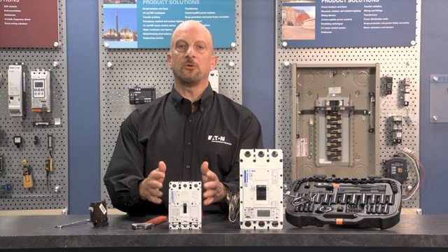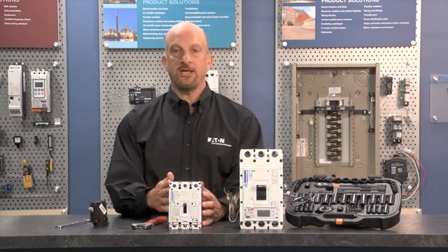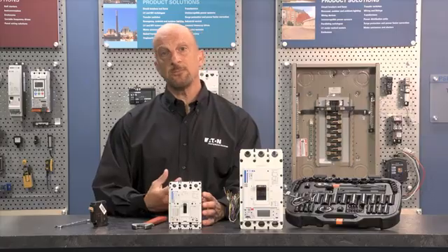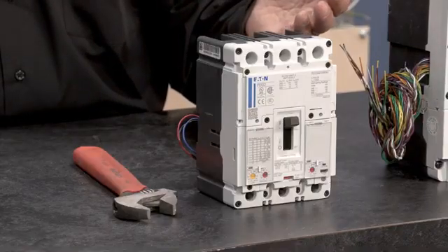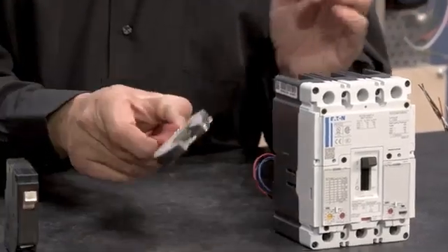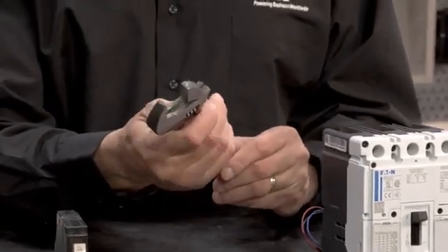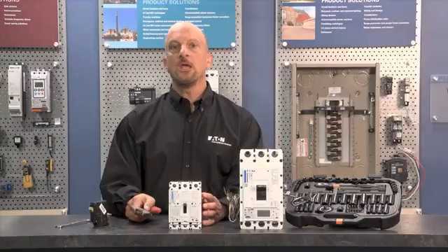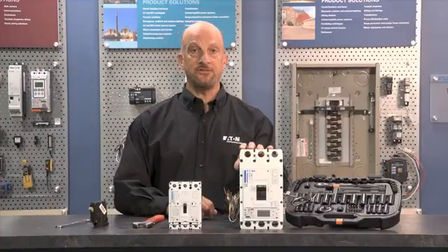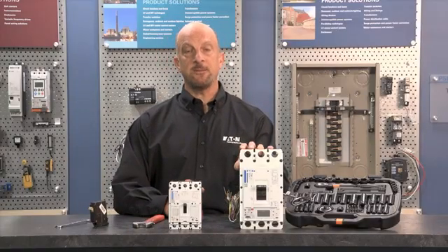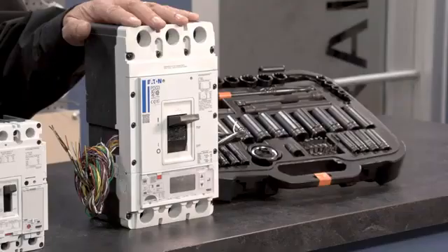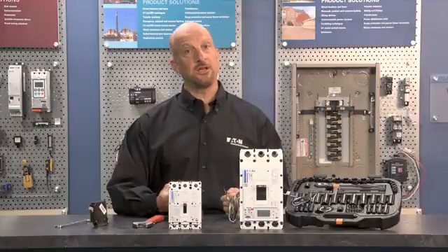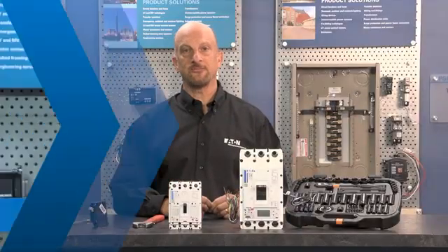The next type is also a thermomagnetic breaker called a molded case circuit breaker, or MCCB. They're used for commercial and some industrial applications, and these breakers would be like this adjustable crescent wrench. The maximum size is set, but you can adjust it down for smaller size settings if needed. Finally, the more advanced MCCBs, insulated case and power circuit breakers, could be compared to this socket set. There are many protection adjustments and almost unlimited flexibility for settings.